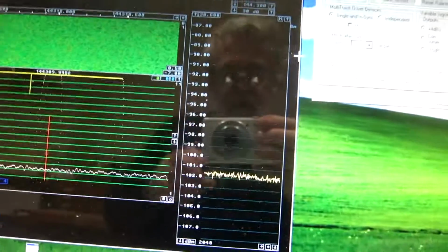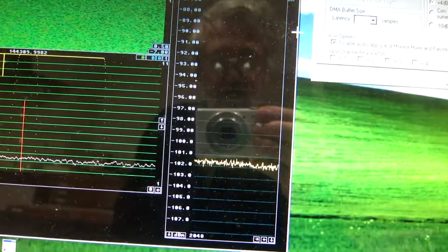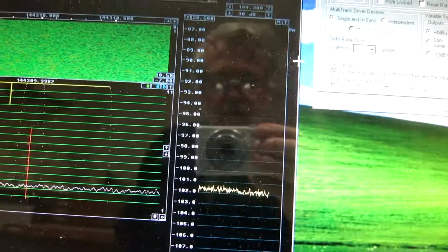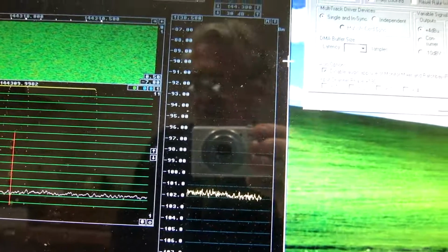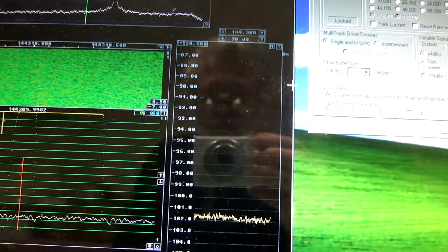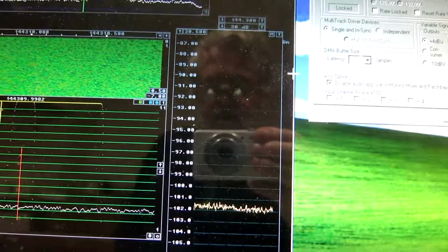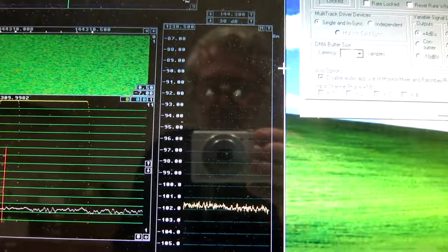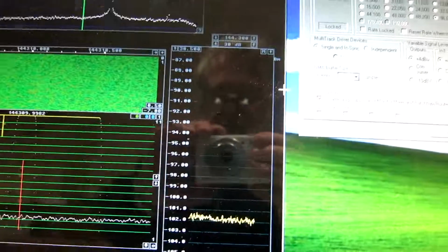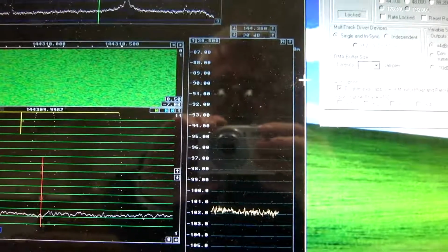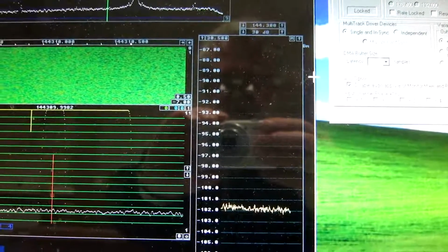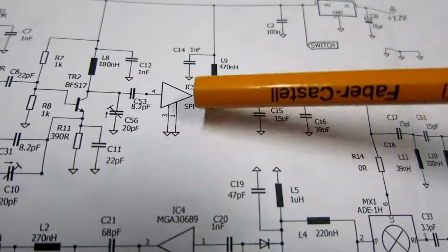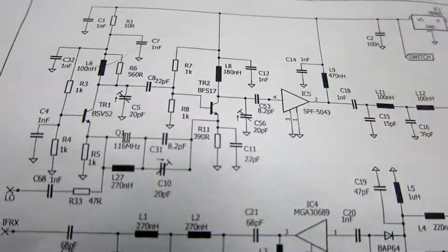This second decoupling also made a significant difference. The noise is now minus 102, that's minus 132 dBc per hertz, and that's actually the same that I saw on the receive side. But I start to suspect that also the receive side suffers from AM noise. So I will continue and look at the further possibilities of decoupling amplifiers. There is one more of these sideband noise modulating devices, and it's in the oscillator.